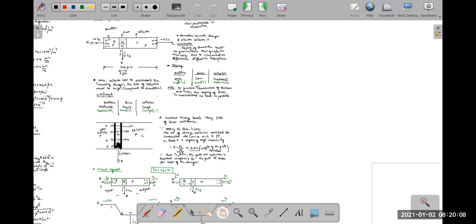The reason was that the base will behave like a region of huge resistance. So the charge carriers from the emitter must be forced to enter into the collector. They must be forced to enter into the collector. We purposefully kept the width of the base as low as possible. And coming to the sizes, the emitter is medium, the collector is large, and the base is small.